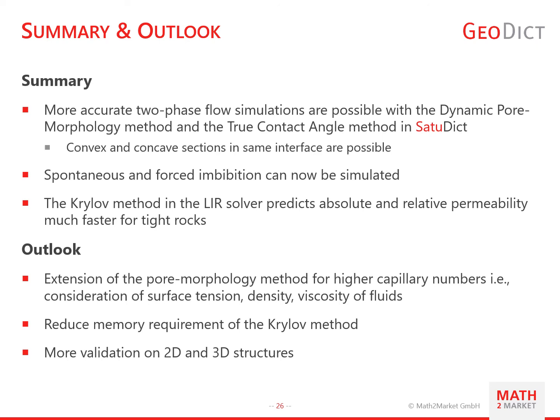In future GeoDict versions, we want to extend the pore morphology method to be able to predict fluid distributions for higher capillary numbers. The memory requirements of the Krylov method will be reduced for the Stokes equations, and we want to do more validations on different 2D and 3D structures to demonstrate its predictiveness.